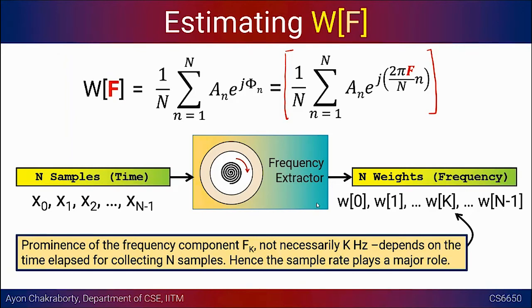And for the sample rate, just to mention, for most of the sensors, when you look at their specifications, they will mention a certain sample rate, right? The hardware will try to give you samples that are spaced uniformly in time, and you will see, this sensor supports 100 hertz, so we'll get 100 samples per 1 second, right? And the hardware will do its best to put them uniformly spaced in time. Okay, and that's how all the intricacies about the ADCs and so on will come into play, how fast they can operate and so on.